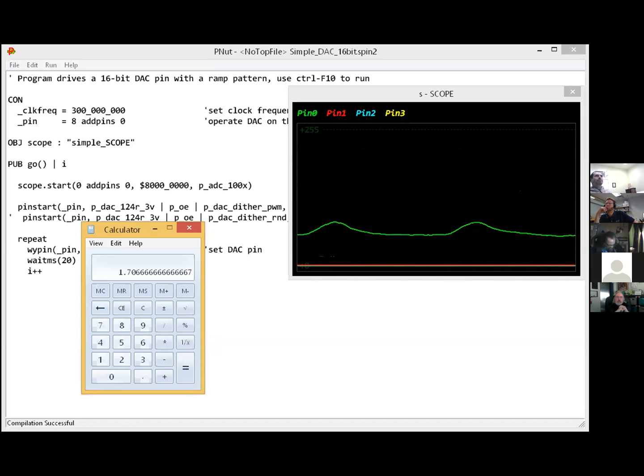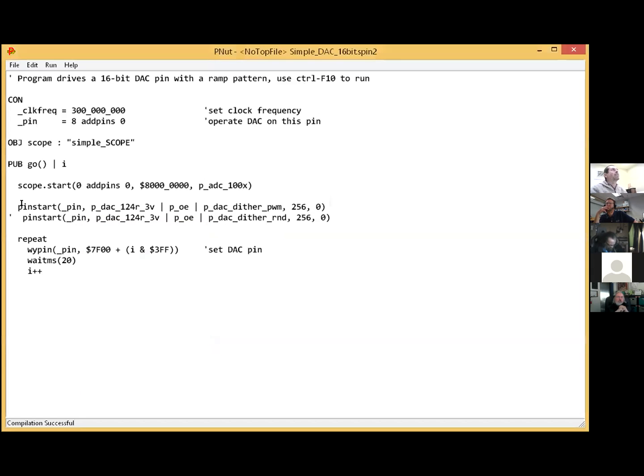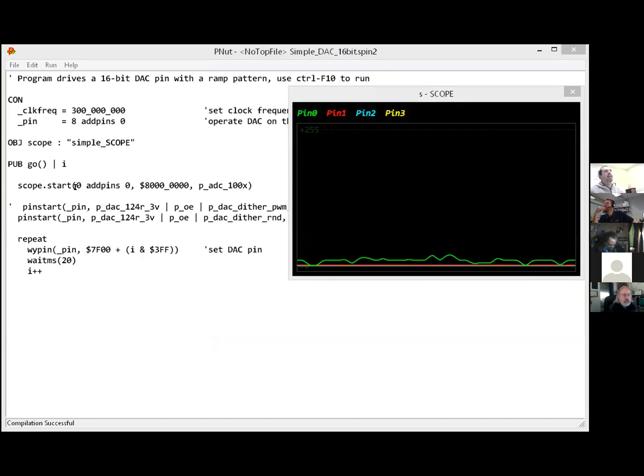Is your dither random? Is that a hardware implementation? Oh yeah, let me go back to the random dither. It's all in hardware. We have a 128-bit, really nice pseudo-random generator that we seed with noise on startup, and it carries on after that. And so here we have it using just random. It looks a lot more linear in slope.